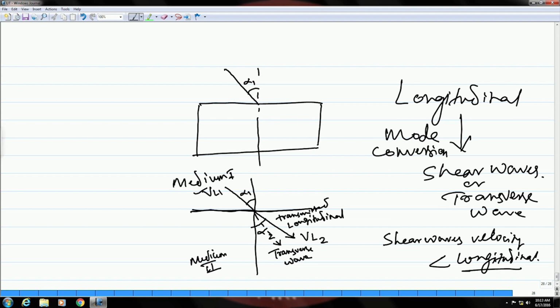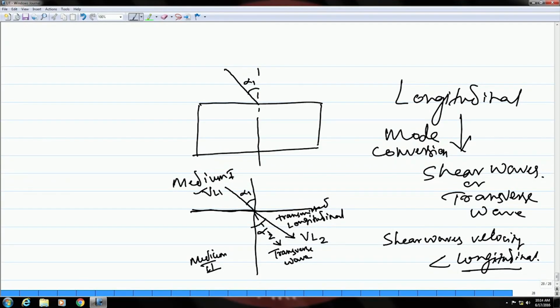So, that means when these waves reflect back from an interface, which could be a discontinuity also, they will arrive at the probe at different times. Okay. So, that means the reflections from the same interface will arrive at different times, and you will see them on the display as the same signal appearing at different times, okay, because the velocity is different.